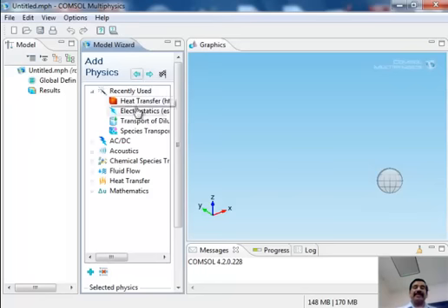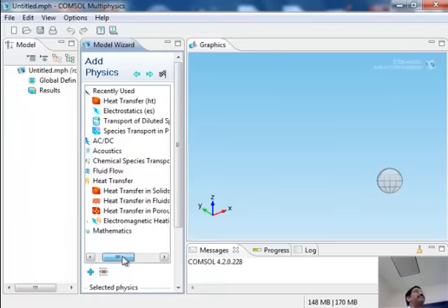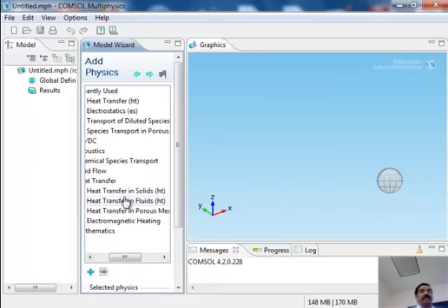When I select that, it gives you many options. Is the heat transfer taking place in solid, or in fluid, or in porous media? Packed reactors are very commonly used, right? So I'm going to say solid, simply heat transfer in solid. And I want you to watch what happens here. This is called the model builder area, where you're building the model by making these choices. The model wizard takes you through the process of identifying the right set of equations, boundary conditions, etc.